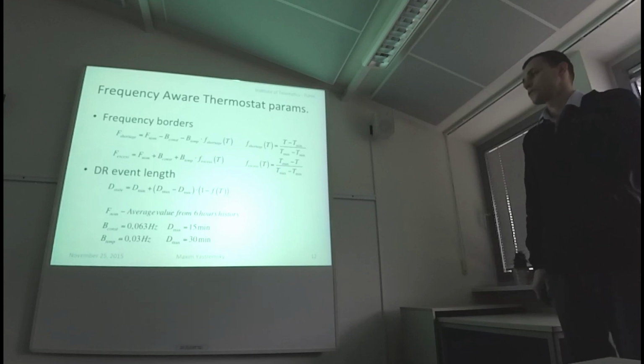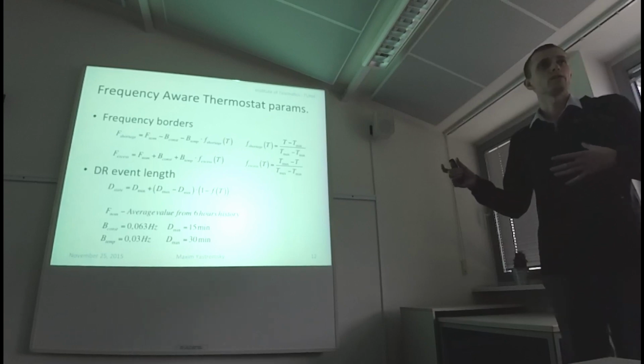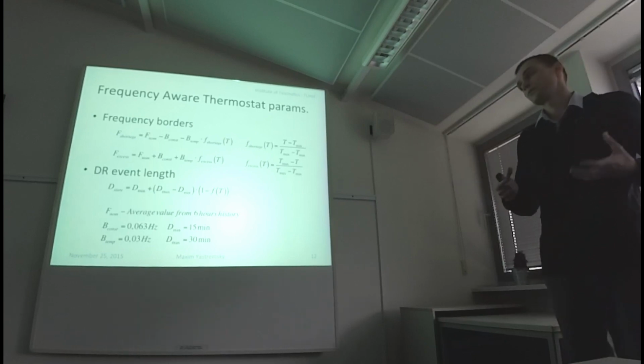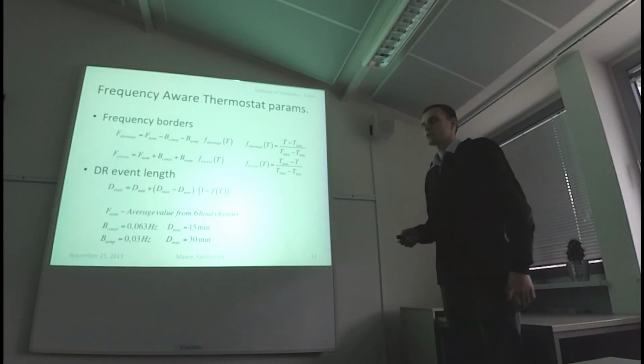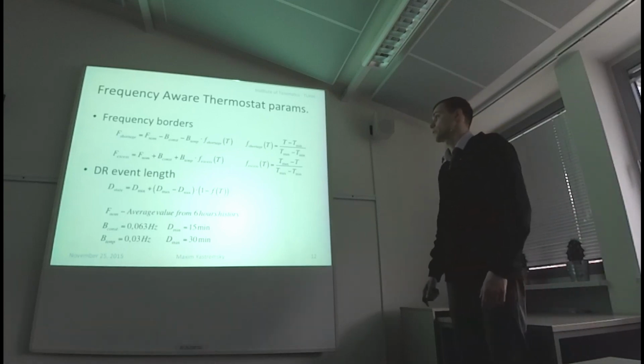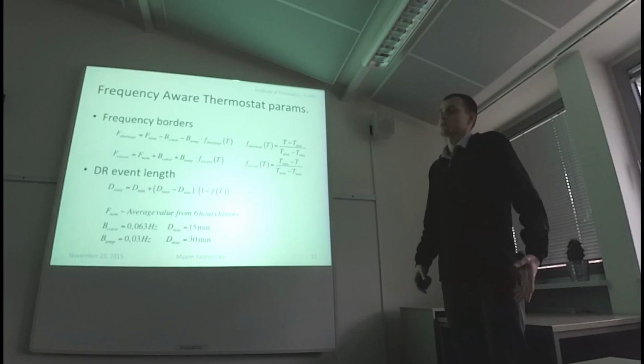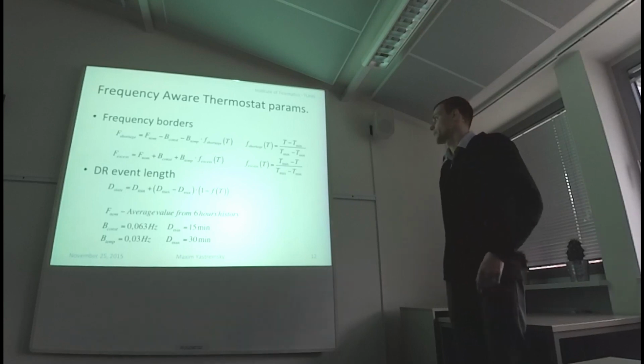I checked many parameters. For example, some of them produced a sequence of uncontrolled demand response states. That basically means too many states, or just those parameters which do not provide any demand response states at all. That means the frequency borders are too big. The duration parameters, minimum duration and maximum duration, were chosen as 15 and 30 minutes.